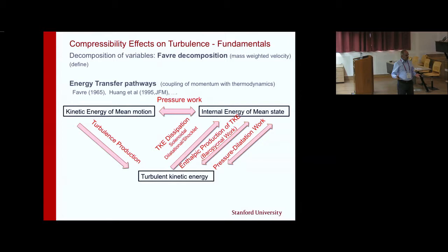This is a process that is active in a non-turbulent flow as well. In an inviscid region of the flow, if Mach numbers are significant, there is a conversion of mean mechanical energy into mean internal energy and backwards as well. Of course, turbulence sort of complicates this picture.